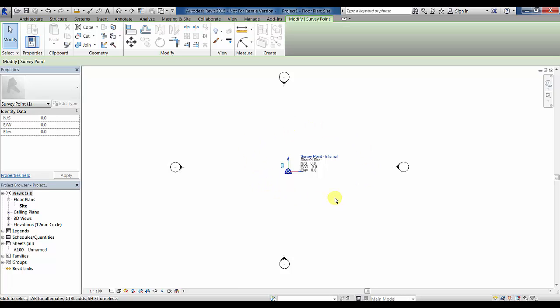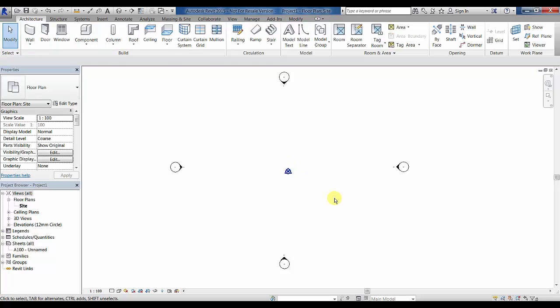This is used in this project only, so allows us to define a local coordinate system and orientation to make modelling easier. This could be anywhere in the project, on the grid line intersection or the corner of a building. It does not really matter where this is, and it's not really important. What's important is that we know the relationship to the survey point, as if we know this relationship for multiple models, we can align them.